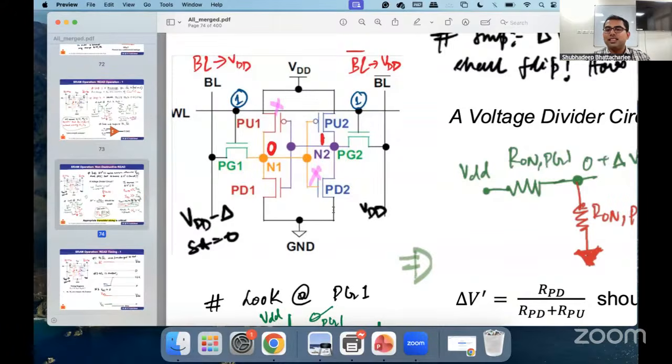So we will discuss this. Abhishek, just a few more weeks, we will discuss which one is used. As I said, digital in-memory computing and analog in-memory computing do entirely different things, so they are used in different places. Digital in-memory computing just does Boolean logic operations, whereas analog in-memory computing does acceleration of vector matrix multiplication. So asking which is used mostly is probably not the right way to approach the question. They are used in different contexts. That would be a fairer answer, to be honest.